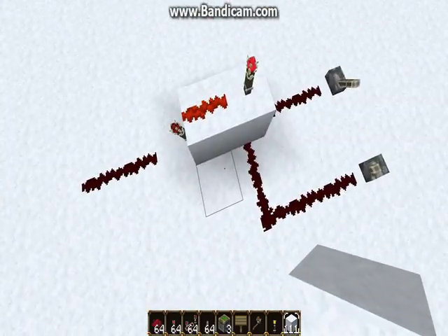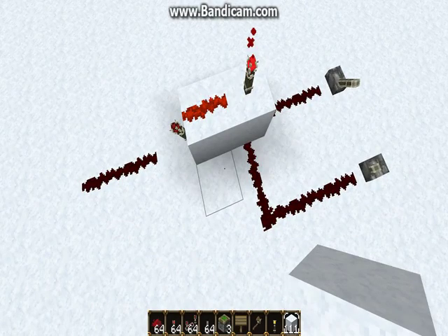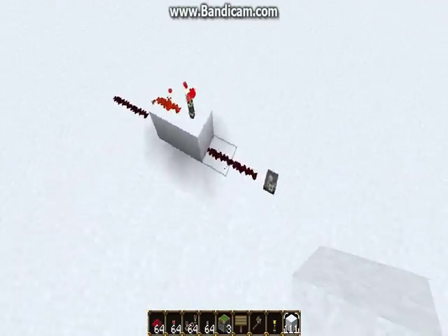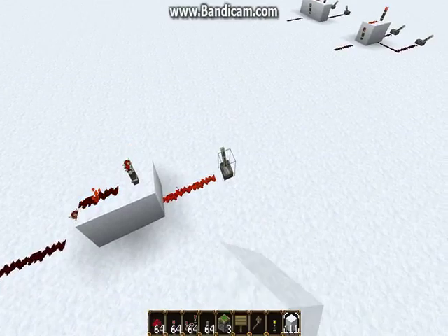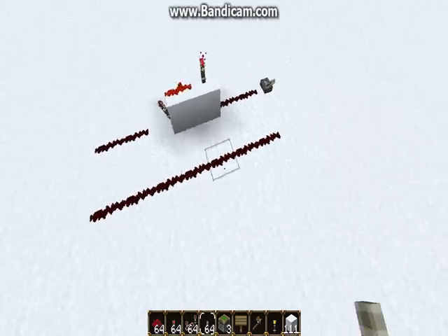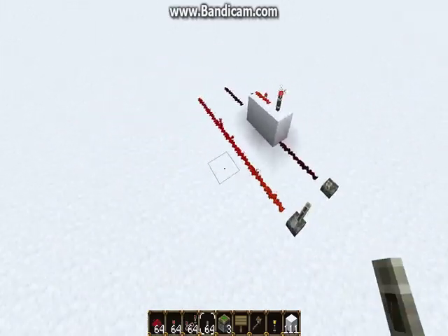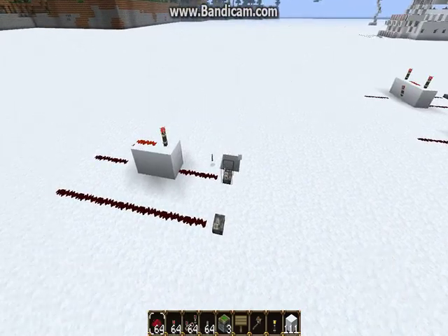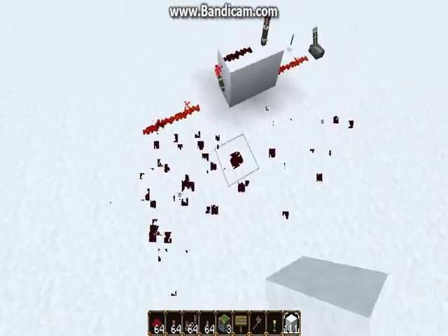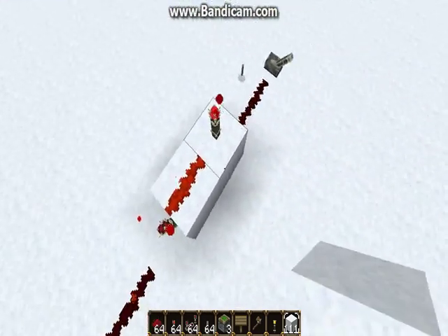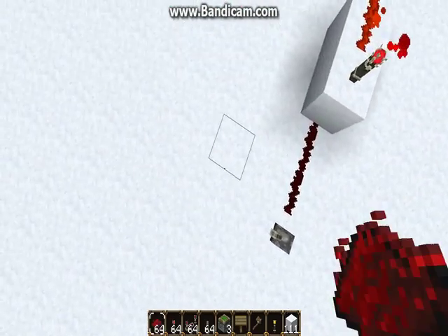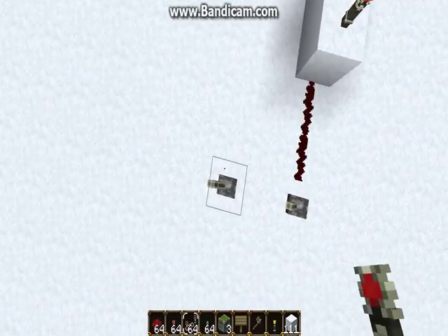So, how do we do this? Well, first off, let's look at a single input OR gate. If we have no input, we have no output. If we have an input, we have an output. And you might say, hey, this is completely pointless. I can make that with a single wire. No input, no output, input, output. And, yeah, you're right. It's technically pointless to have this. But it offers us something really unique. It offers us the option of doing something with the inverse of whatever our input is. And that's, as it turns out, really critical to making an XOR gate work.